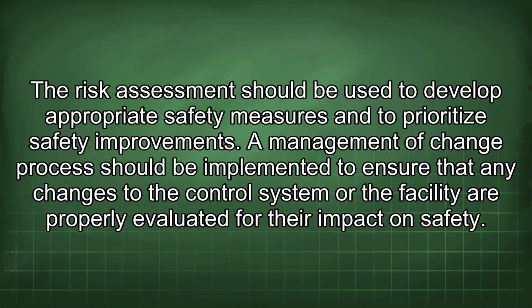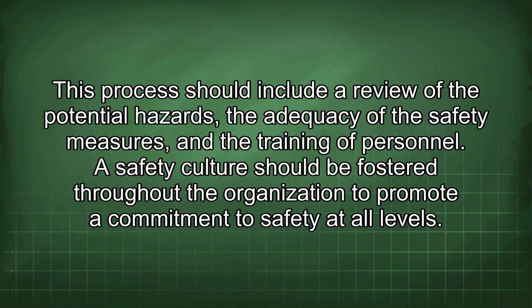A management of change process should be implemented to ensure that any changes to the control system or the facility are properly evaluated for their impact on safety. This process should include a review of the potential hazards, the adequacy of the safety measures, and the training of personnel.